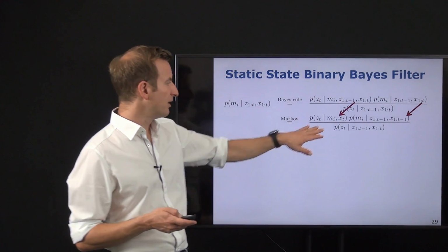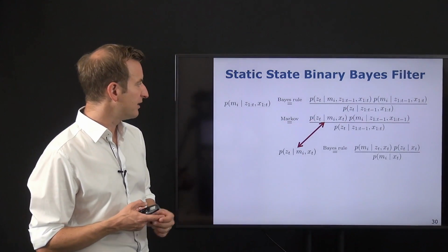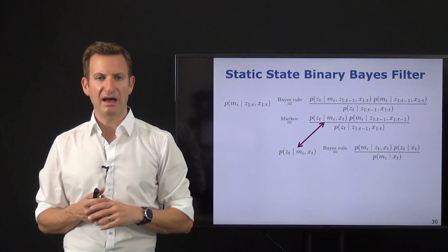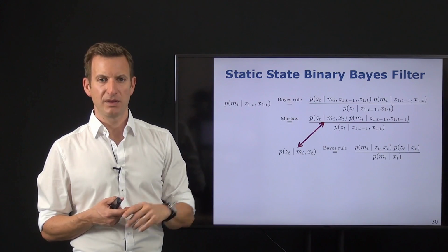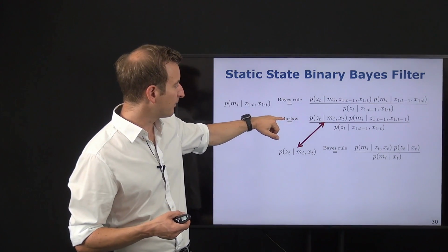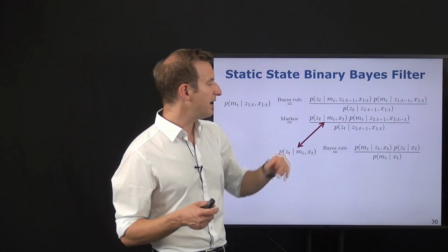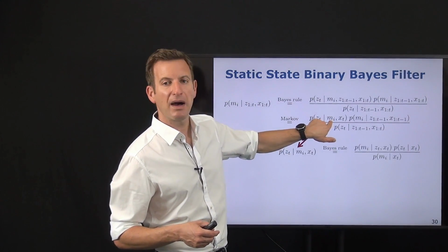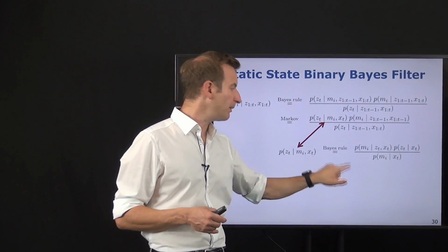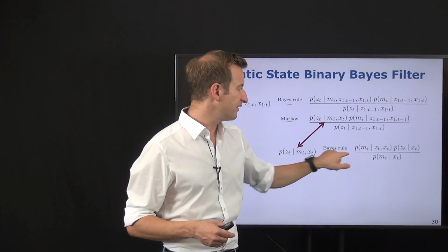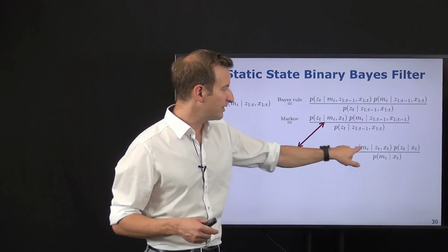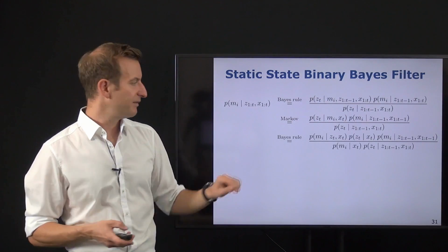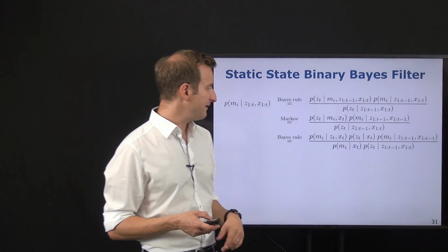And then we want to further simplify this expression by using the first term again and applying Bayes rule again, basically swapping that back after having exploited the Markov assumption. So we exploited the Markov assumption and then apply Bayes rule for the first term again, now swapping zt and mi. So you can see here, this is the application of Bayes rule for this term. We take this equation and put it in here, and then we have this term consisting now of 5 elements.